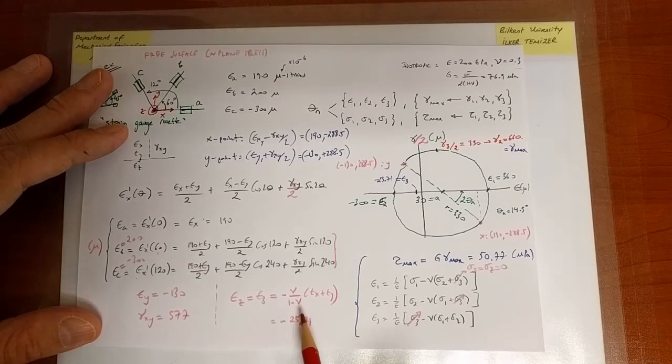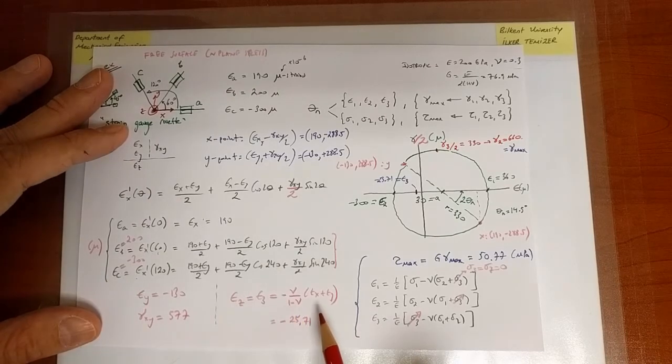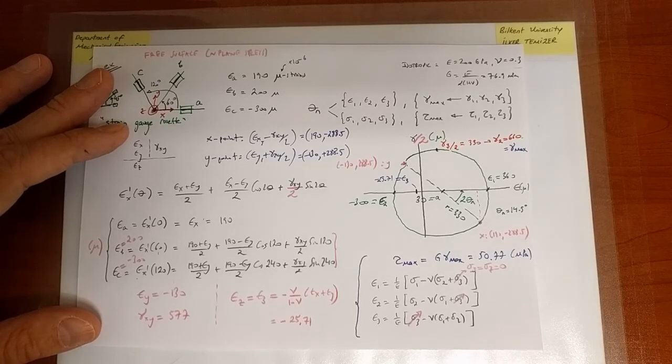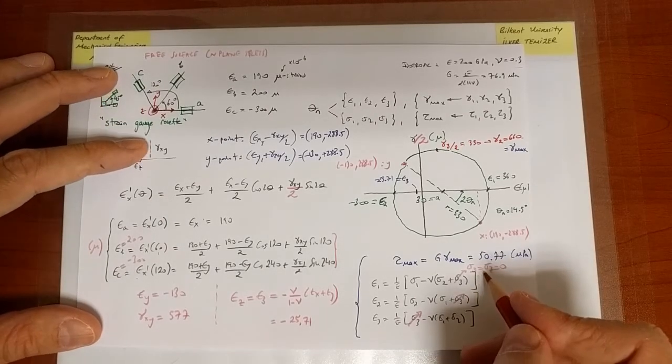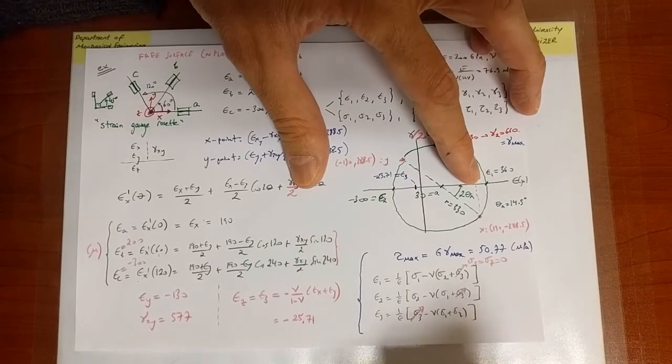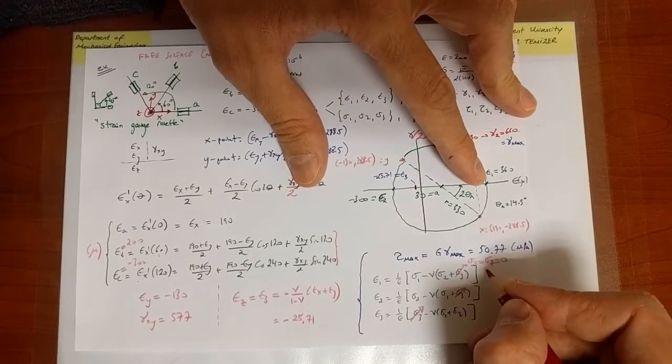In other words, for a state of plane stress, you have a generalized plane stress scenario where, in terms of epsilon x and y, this is the value of epsilon z. So epsilon z is equal to epsilon 3, so we're not going to have any new knowledge emanating from that final equation. So these two equations are all that we need presently. We've already made implicit use of that one.